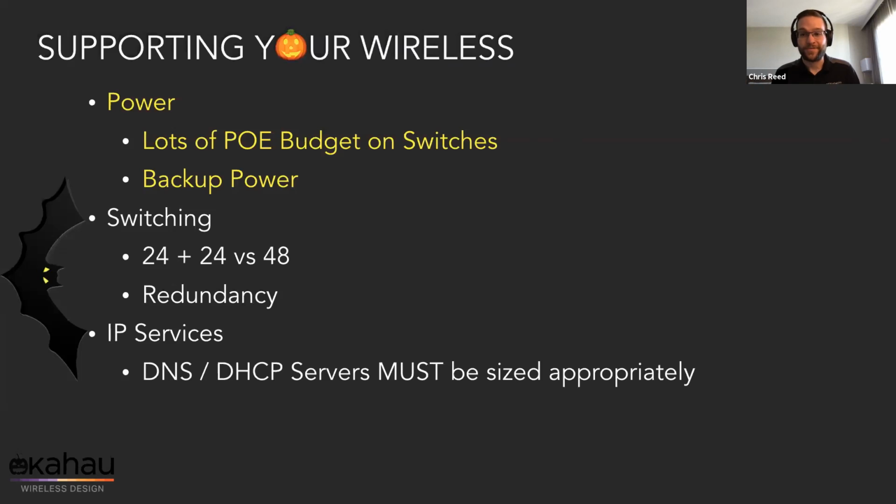So you've got to plan for that on both the UPS side as well as the mains power side. Don't just assume that you've got enough power in an area. It's one of the few areas where you may actually be using PoE on every port, and trying to find UPSs that can service 5 or 6 switches in a closet.